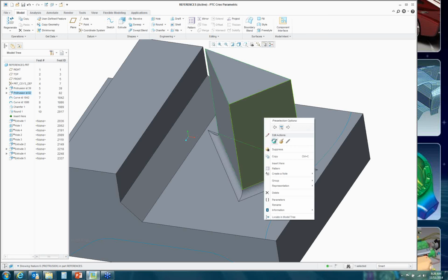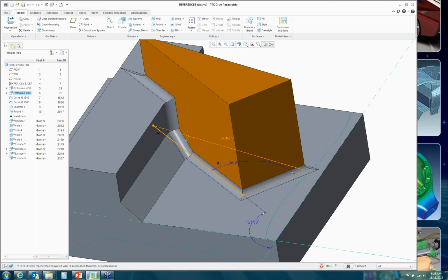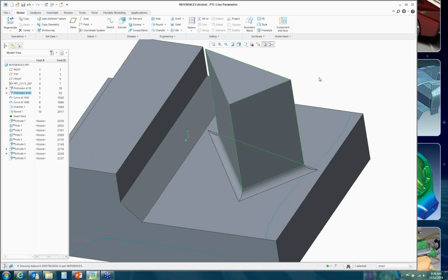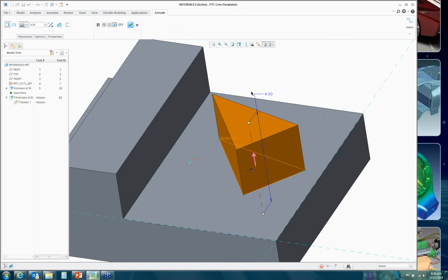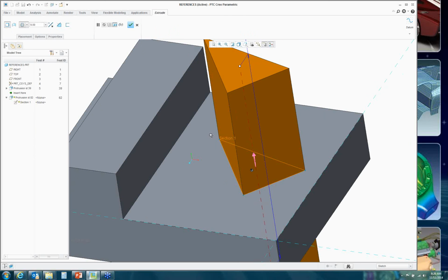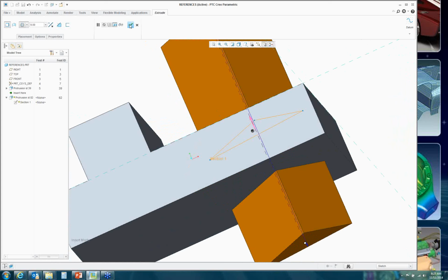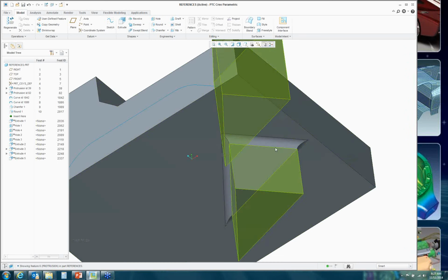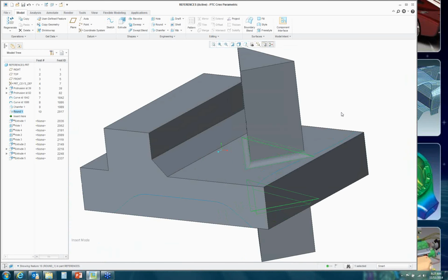If I say edit, and I drag this up onto the ledge here, I get all of those rounds. Or if I say edit the definition, and I change the depth option to say symmetric perhaps, and I drag that feature out both sides of the model, of course, again, because I said create the round everywhere that feature intersects the part, I get a round now on both sides of that model.